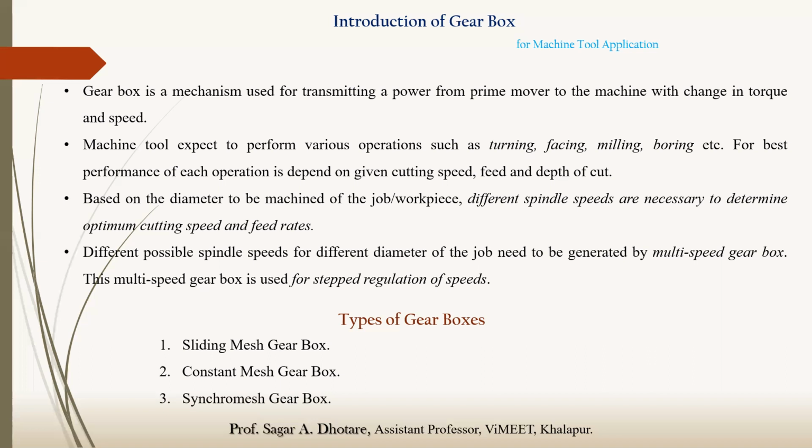If we go to the specific machine tool application, there are a few different operations which we are going to perform, that is facing, turning, milling, boring, and each operation requires a different cutting speed, feed, and depth of cut. So we have to perform a variation in the torque as well as the speed.